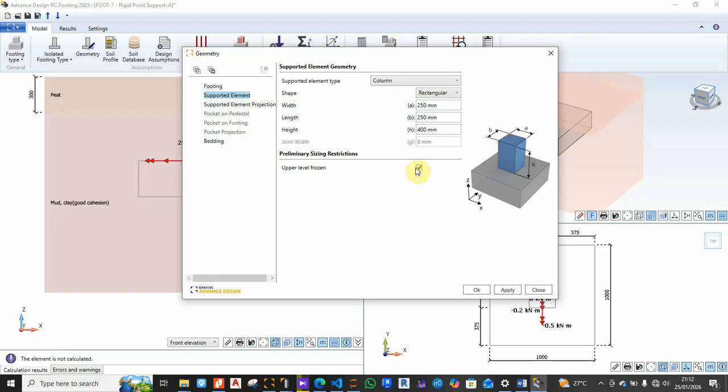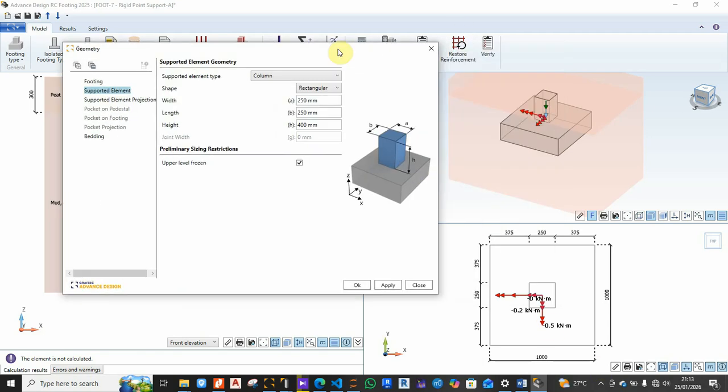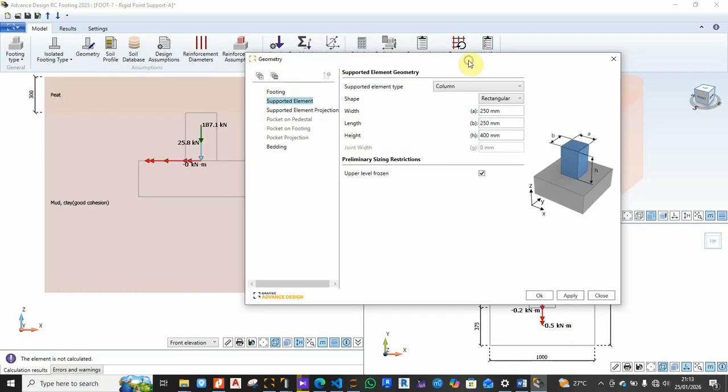This is just for representative purposes, because actually the loads that are coming down due to these elements and the other elements has already been taken into account. As you can see here, these are the loads. When you look very well, it's the same load that we had at the bottom of the column, 187. So that's the load that's falling on the footing.